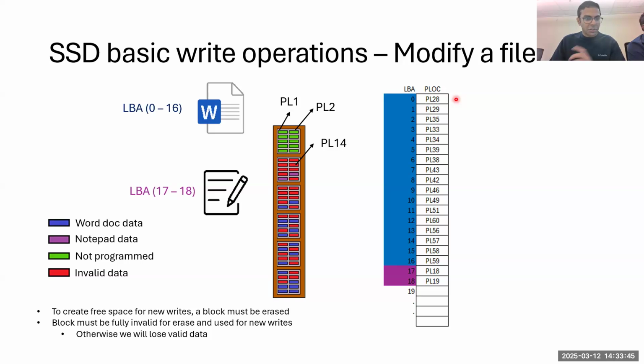One thing to note, so it's good that you brought this up. Let's say you shut down the computer. All of the indirection table contents that are in the DRAM of the solid state drive would be written to the media itself. There will be some section in the solid state drive allocated to store system data, including this indirection table. This will be written to the solid state drive on a periodic basis.